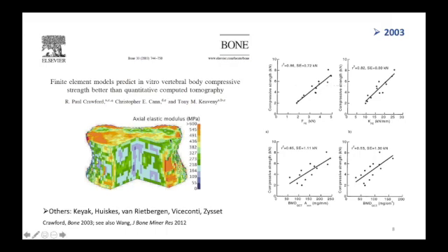We'd also been doing computer modeling, very sophisticated computer modeling, but we tried this voxel approach where, instead of trying to model the bone with curved elements and use parametric, quadratic finite elements, we just said, look, let's use the so-called voxel approach, which is you make a finite element out of each imaging voxel.